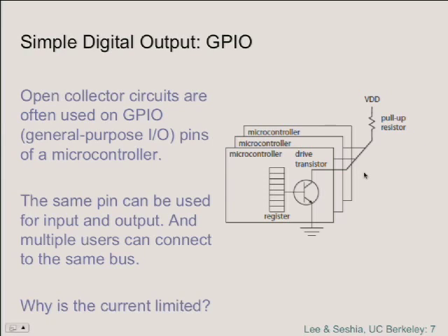One simple mechanism that it might do is it might be that every item on the bus has a unique ID, and they pull down bus request lines that assert that ID, and then the arbiter will respond saying, okay, the one with this ID is the one that's got the bus now. Okay. So the exact protocol there very much depends on the bus protocol. In fact, what a bus protocol is mostly about is that arbitration. How do different devices get access to the same bus? Okay. Does that make sense?